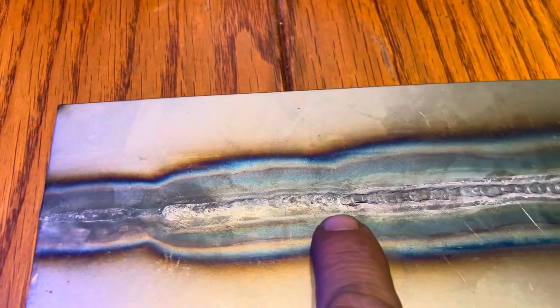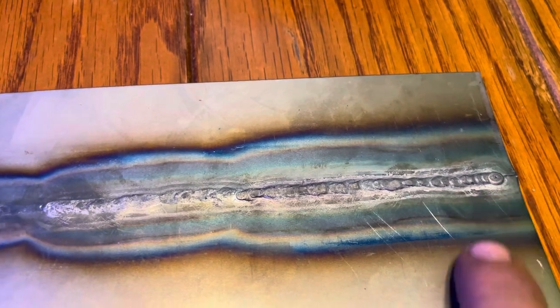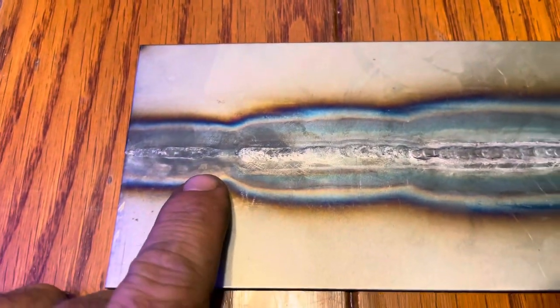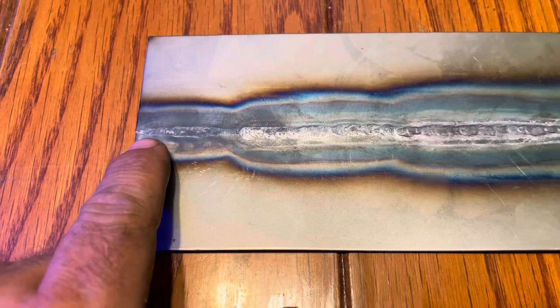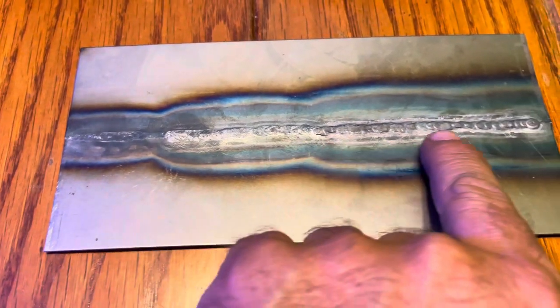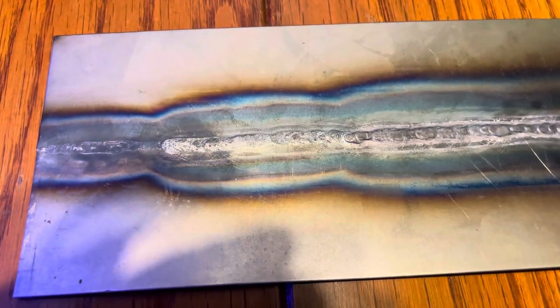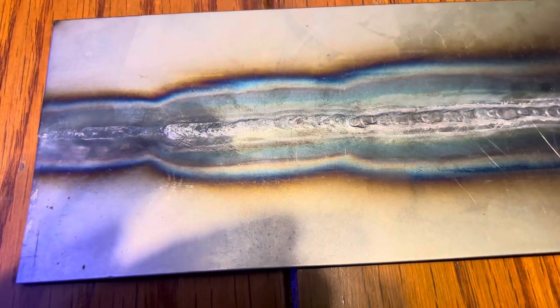So here's our part here. This is just a fusion. This is where I added the smaller filler wire, and this is where I jumped to the great big filler wire. As you can see, we got 100% penetration all the way down it. Now, I kept the amperage on the machine the same. I just set it to where I could hold the pedal down and fuse, and then started adding filler wire, and then added the larger filler wire. That way the amount of input of temperature that I was using always stayed the same.